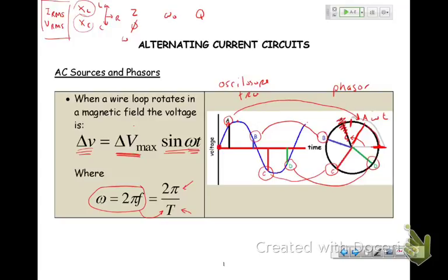I'm going to give you an LRC circuit. I'm going to say, hey, what's the resonant frequency of this? I'm going to say, by the way, at this other frequency, what would be your capacitive reactance? What would be your inductive reactance? What would be your impedance? And then, by the way, what's the quality factor? If I give you these other numbers, what's the quality factor? So I can't get through this bit and not ask you about a tuning circuit. So it's money in the bank. Okay? Questions? Let's end it there then.